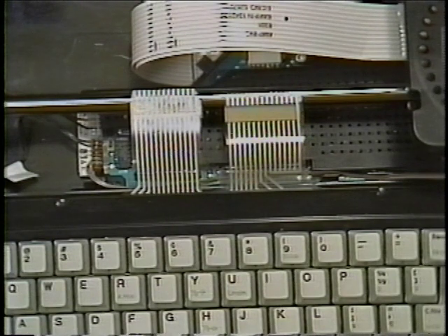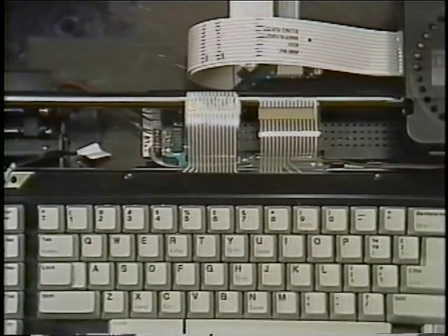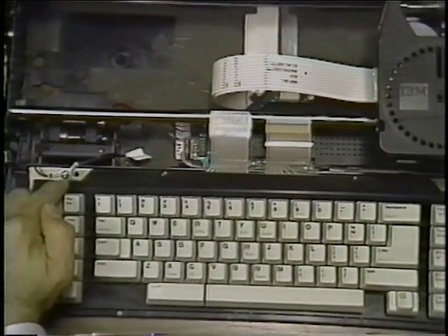When servicing this machine, never place the keyboard cables on top of the front carrier shaft as shown here. Grease and dirt from the shaft will contaminate the contacts on the ends of the cables.